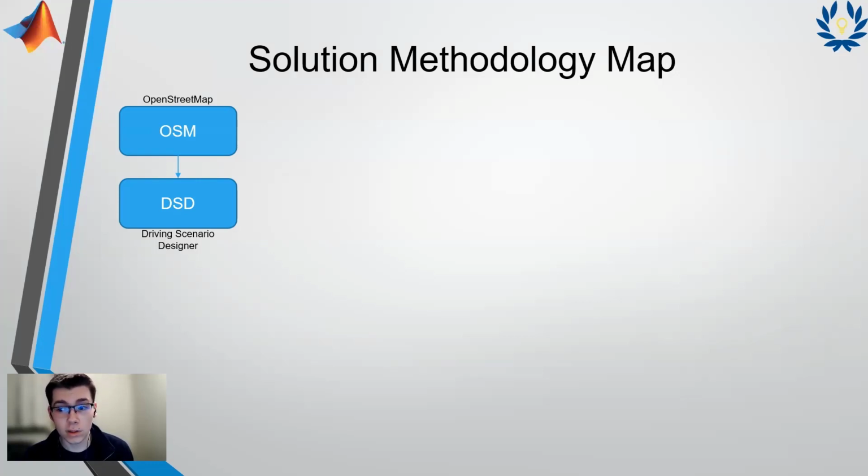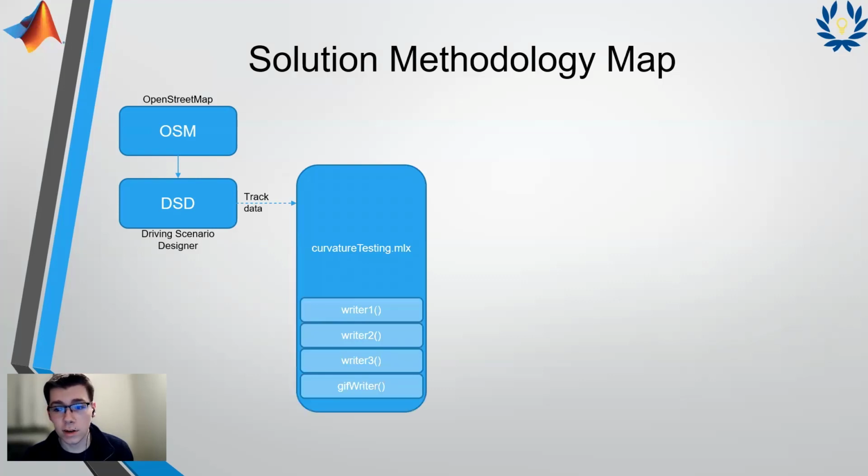Moving on to the bulk section of the code, let's start at the curvature LiveScript file. The LiveScript file allows for user input to configure the optimization and velocity profiling, as well as the graphical outputs they want. We'll go through this in detail a little bit later, but in short, LiveScript will import the .m track files and parse the data to create a set of points that represent road boundaries and the center line. The center line, as well as the user-defined optimization parameters, are then passed to the discrete waypoint optimizer file.